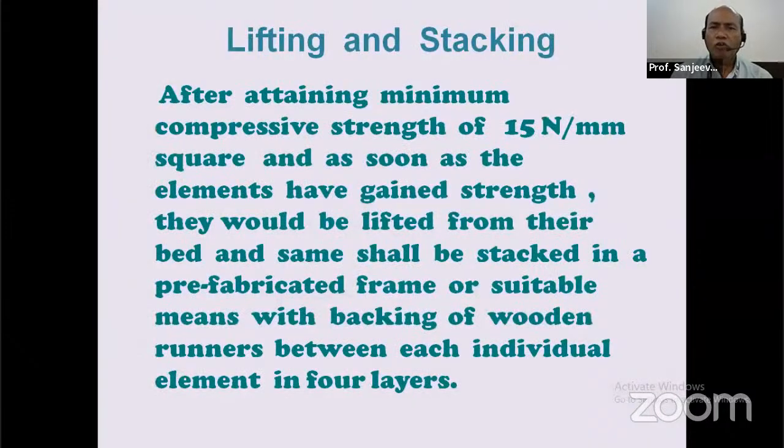Then lifting and stacking. After the curing work was done and repair work was handled, and everything was achieved, now lifting and stacking. After attaining minimum compressive strength of 15 Newton per millimeter square, and as soon as the elements gained strength, they would be lifted from their bed, and stacked in a prefabricated frame or suitable means with backing of wooden runners between each individual element in 4 layers.